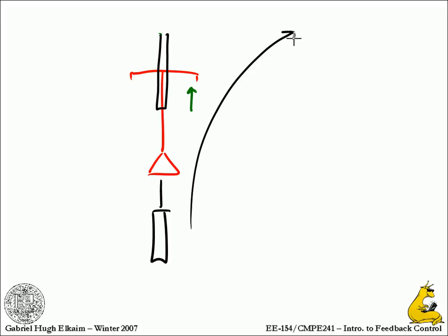So what doesn't work? Would that work on a skateboard? Will not work on a skateboard. Why? Because four wheels? Because you can't push on the wheel on skateboards. This is just the most famous example. On a motorcycle, by the way, this is referred to as countersteer. So on a big motorcycle, which has a hell of a lot more inertia in the wheels, what happens is that the sequence is this. You're going along fast. You want to turn to the right.